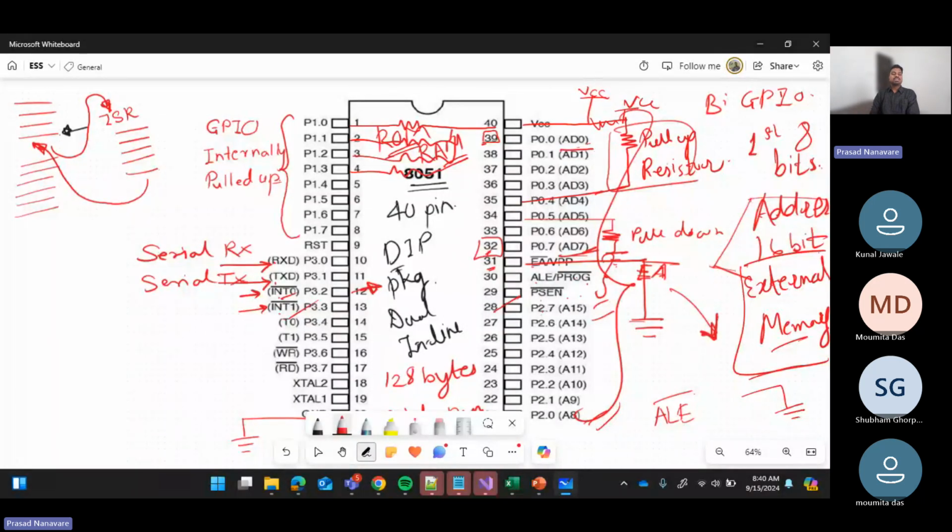Now do you understand what an interrupt is? After an event happens, we perform some task apart from our regular code, okay, and that is called the interrupt service routine. Okay, and this interrupt service routine is another code, which executes, and then again our regular execution happens. Okay,